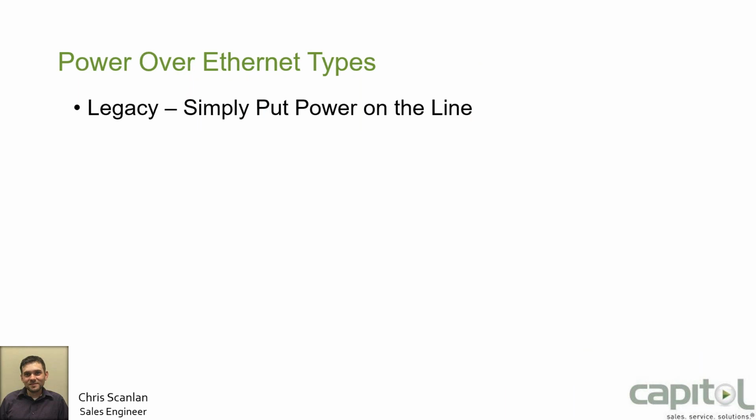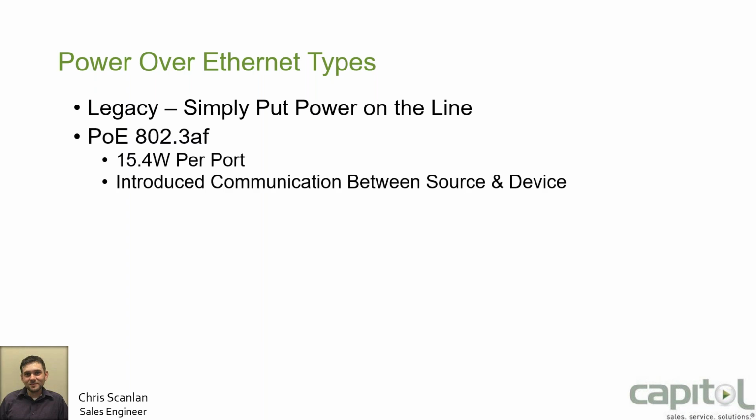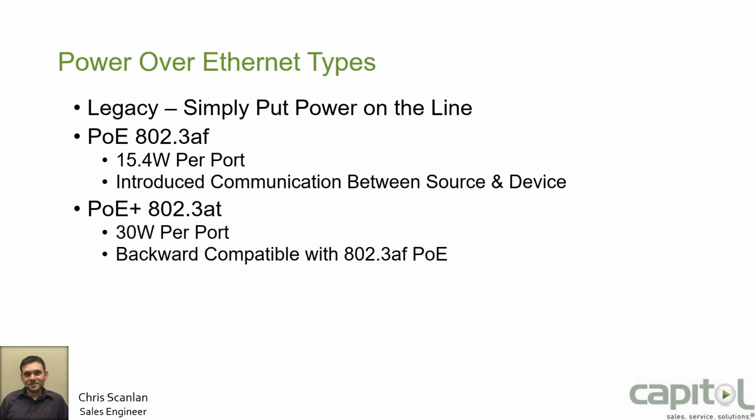Now, another thing that you guys may not know is there's different types of PoE. There's legacy, which is your standard supply power over the line. There's standard PoE now, which you will see PoE or PoE plus. You guys may not know what PoE plus is. PoE is 15.4 watts, okay, per port. PoE plus has the ability to do 30 watts per port, and it's backwards compatible.